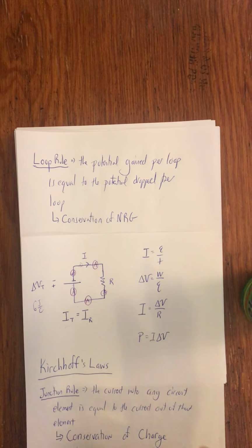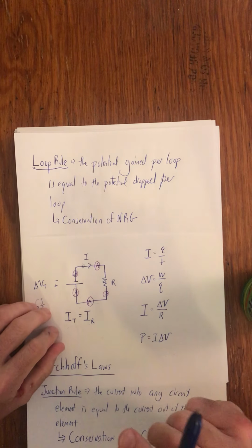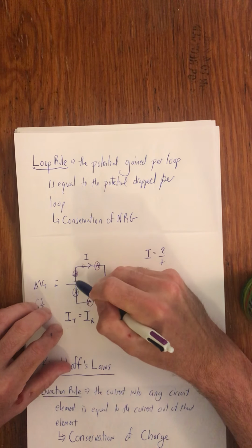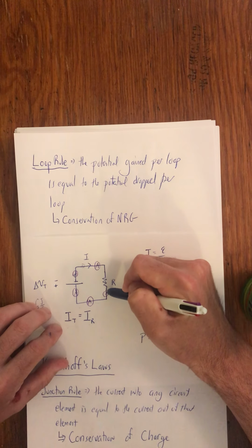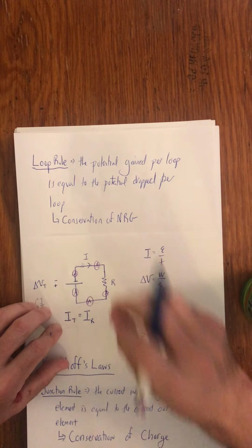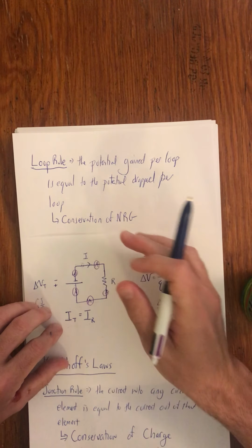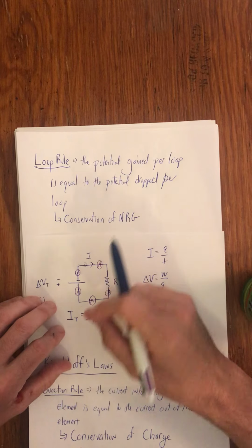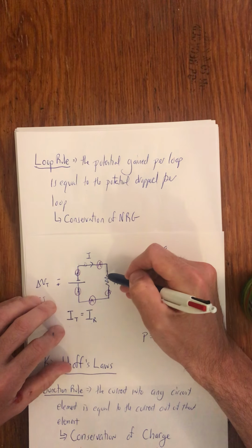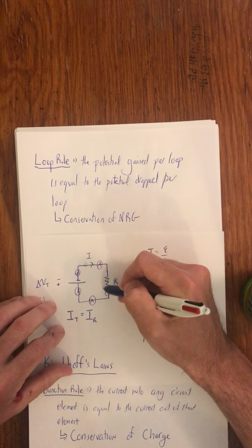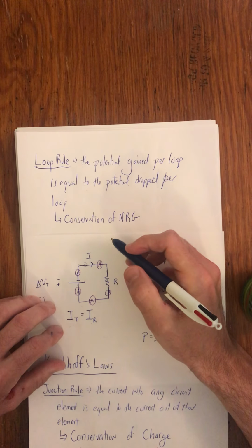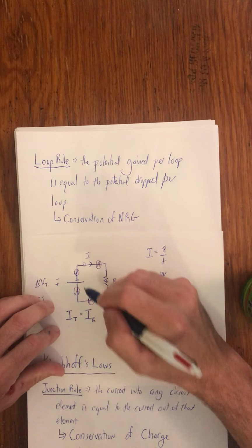Now, so there we go. Now, I'm going to drop a little bit of truth here. It actually picks up 6 joules, drops off 6 joules, right? But here's the thing, in reality, remember that all of our wires, not technically, I gotta stop saying that, they actually are resistors themselves. Every wire is a resistor. It's just that the wires have such little resistance compared to this that it's almost irrelevant. For example, if this resistor was a 100 ohm resistor, this length of wire might only have a 0.002 ohm resistance.